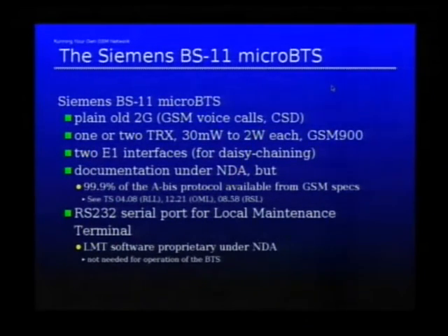The interesting thing for the base station transceiver is that you can set up the power which it uses on the output. There are 4 stages between 13 milliwatt and 2 watt, and you can choose which stage it uses. So even if you should not try it at home, if you try it, turn it down to 30 milliwatt, then probably you don't disturb too many people.